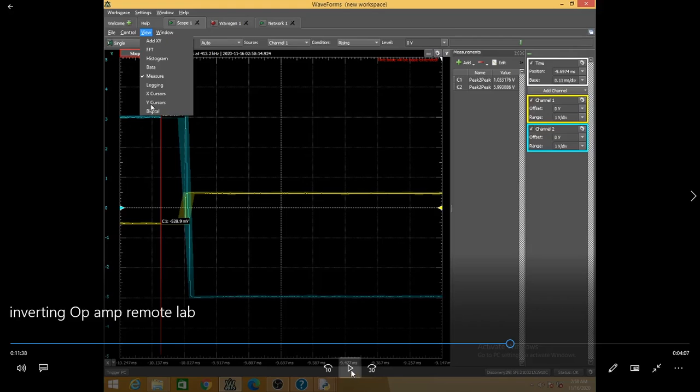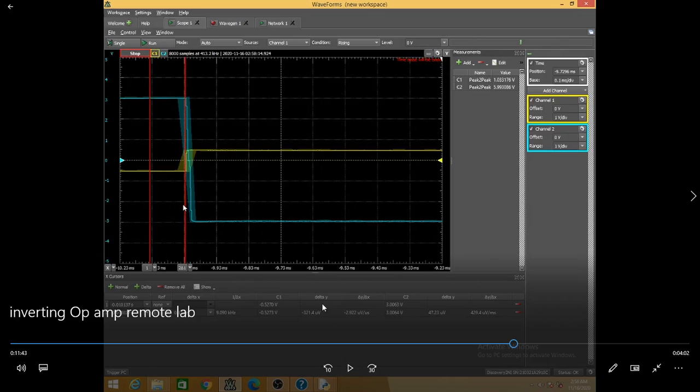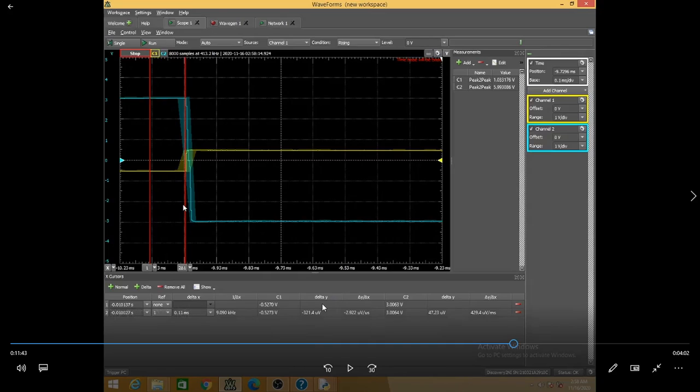We can actually measure what the slew rate is. So you can see how to measure it. So 500 millivolt per second, sir? Either it can be 500 millivolt per second or microsecond, sir. 500 millivolt per microsecond. No, it should take very little time. If it takes a second, then it will be a very slow op amp. Either it is volt per microsecond.